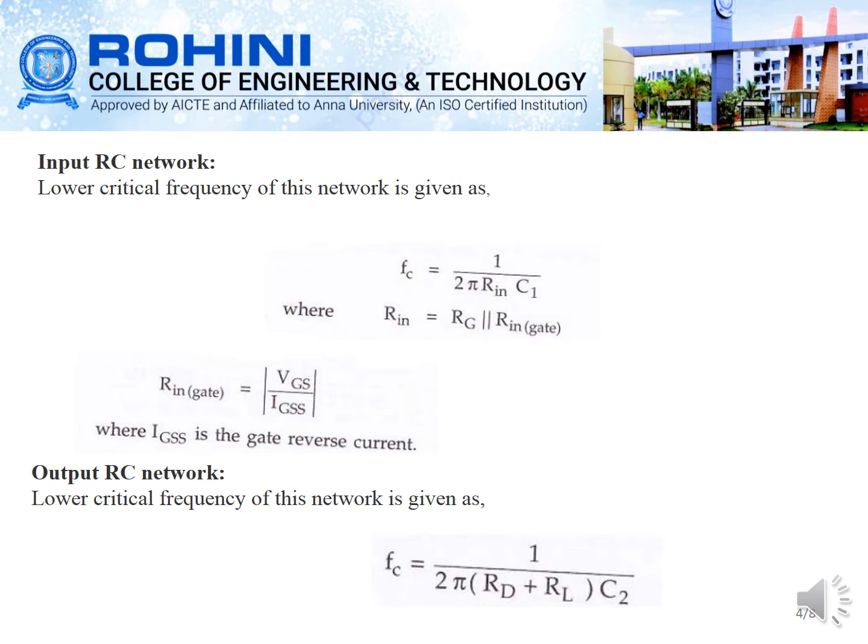When calculating the frequency response, at the lower frequencies there will be a steady increase, and this steady increase goes up to only 70%. It cannot reach 100%, because up to 70% there is an increase in the voltage gain. After that the voltage gain stays constant for some frequencies. Then at the higher frequencies there is a reduction in the voltage gain, that is, it starts decreasing. So we get a curve of increasing output, then constant voltage gain, then decreasing.